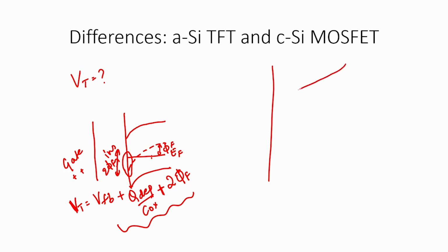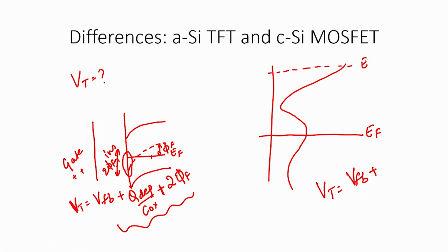Instead what we have is a conduction band and states inside the band gap, and let us say this is the Fermi level at flat band. So, yes, you do have flat band. The first milestone to cross is the flat band, but threshold voltage is defined as that voltage wherein the Fermi level gets close enough to the conduction band edge, so that the extended states above the conduction band edge are populated with some amount of free carriers that enable a measurable level of conduction.